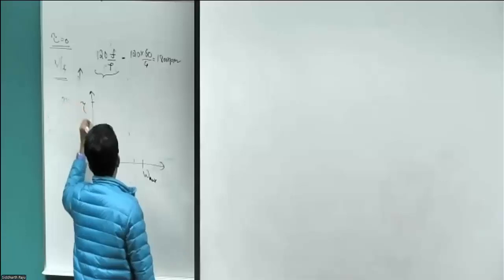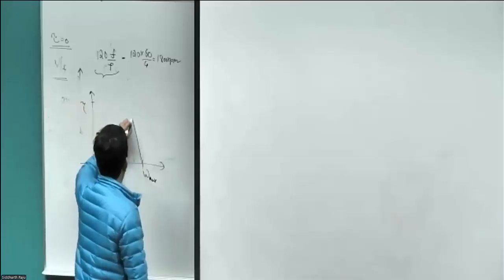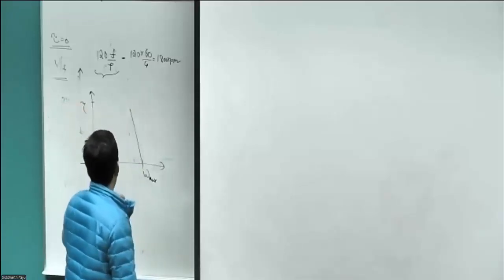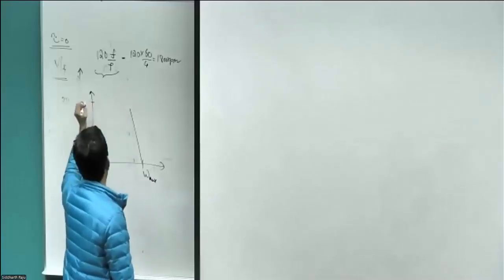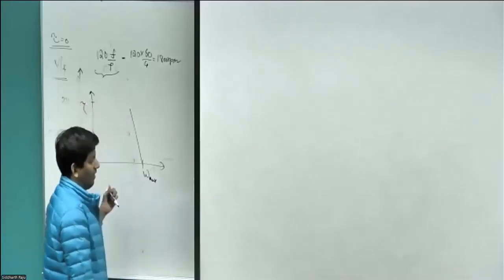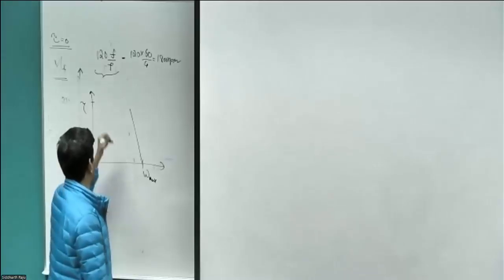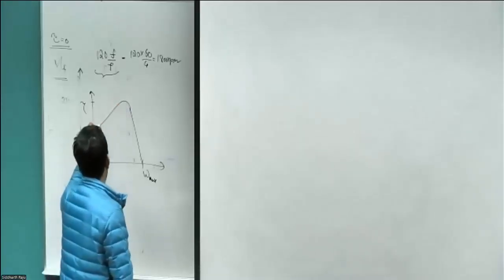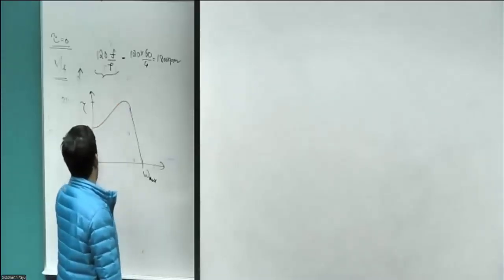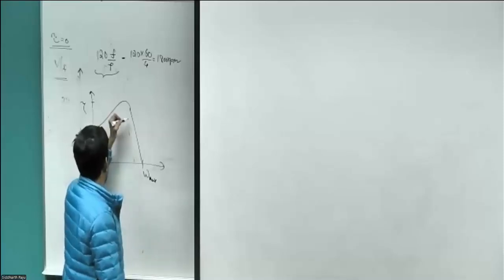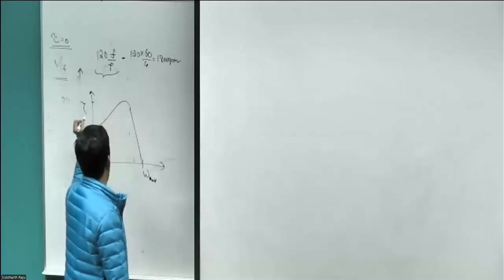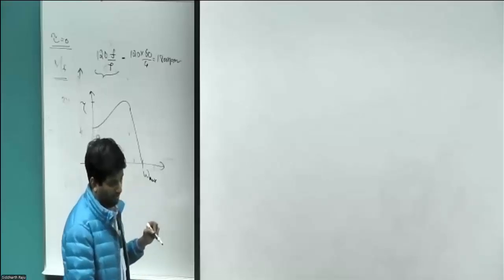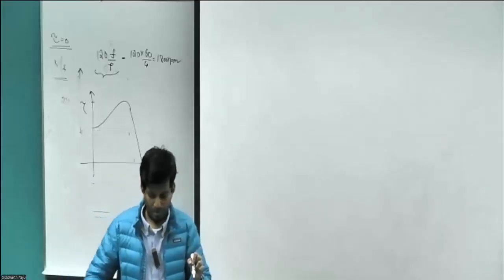And as I start increasing the torque, the speed starts to gradually drop. If I exceed the maximum amount of torque that can be generated by this motor, the motor would come to an abrupt stop. And if I were to reduce the torque again, the motor would go back to operating at the speed at which it could support the torque that is being requested by the load.